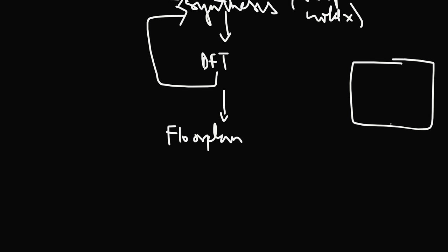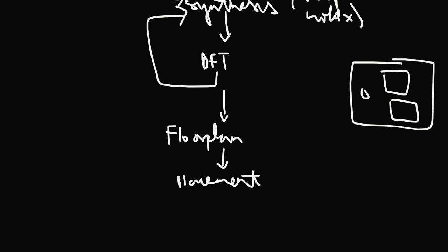We have some parameters like aspect ratio, the height to width, and based on that we come up with the actual shape of the chip, and we place some of the macros, like memories. All this plays into the initial floor planning stage itself. Then we have the placement stage, where the actual design functional cells are placed into the chip.